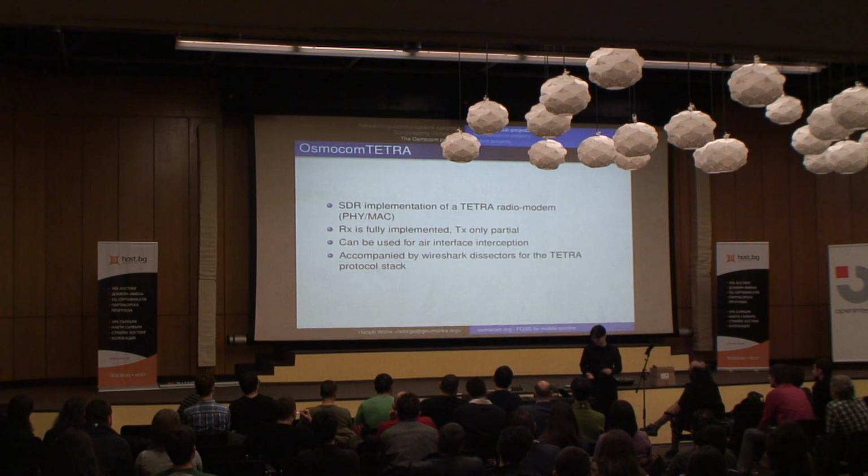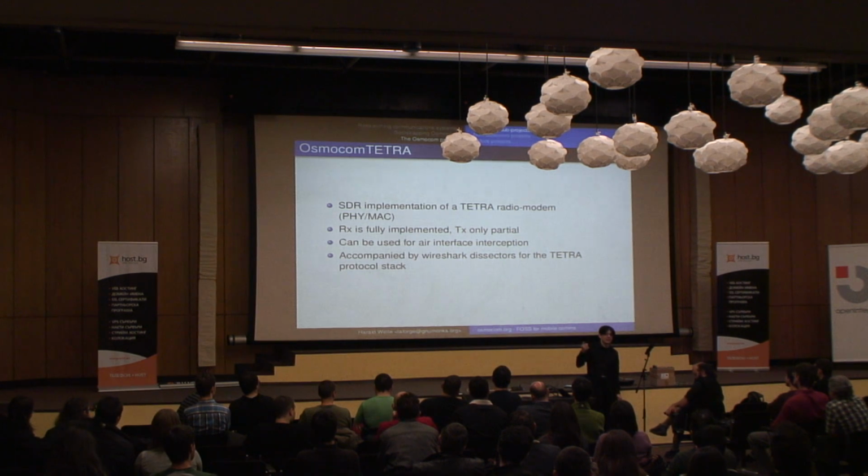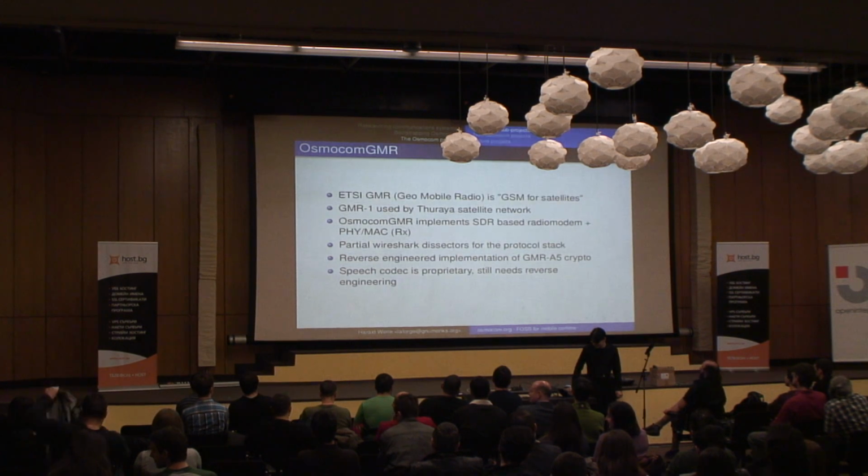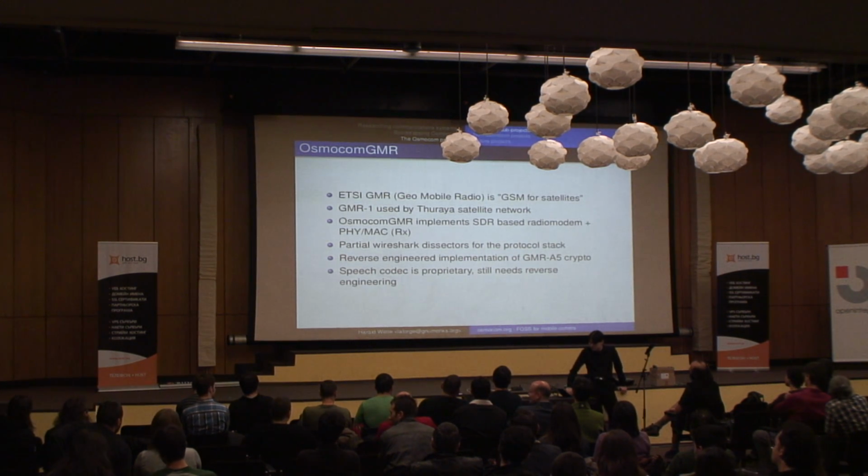So now you can basically use a $20 USB device, you put it in your PC, you start the software, and then you see all the TETRA messages in Wireshark and can explore what's going on. And the funny part is that in Germany, it seems only the public police network uses encryption. All the other networks, even on airports and harbors and other things where you would say this is security critical, it's completely unencrypted, and you can just listen to all the communication.